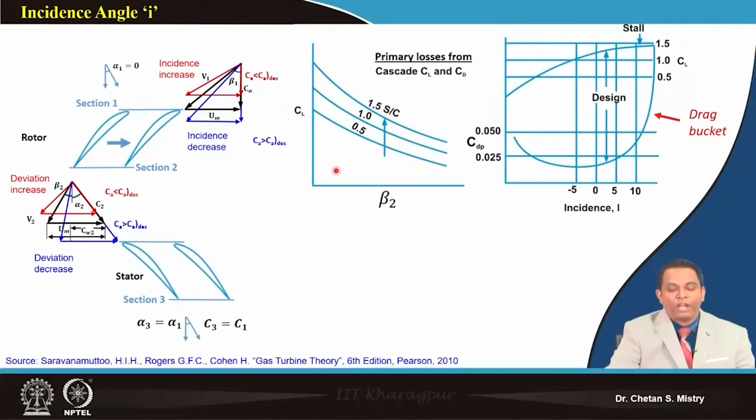Now we have our fundamentals available. What we can see here is the change of incidence angle with the change of drag coefficient CD, and this represents my lift coefficient. So these are the characteristics of aerofoils. Now if you look here, suppose somewhere here I have some design point, which I have already designed for. What happens if my incidence is increasing? Say this is the increase of incidence, plus 5, plus 10. We can see that it gives me a higher CL.